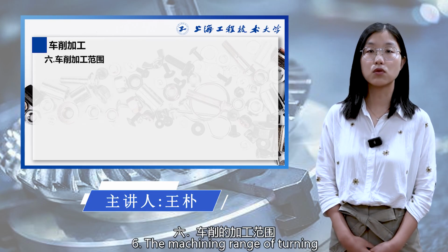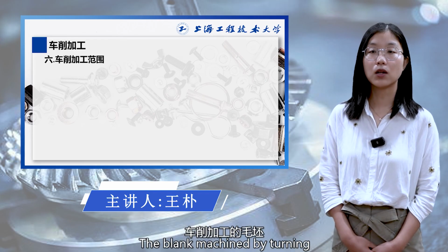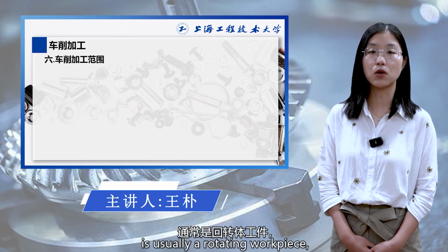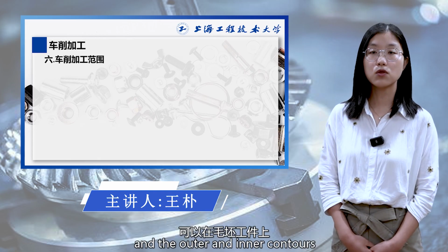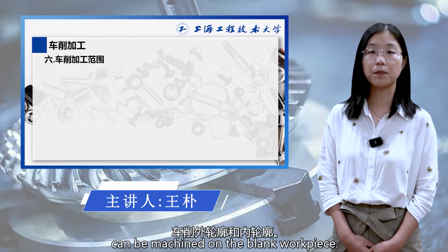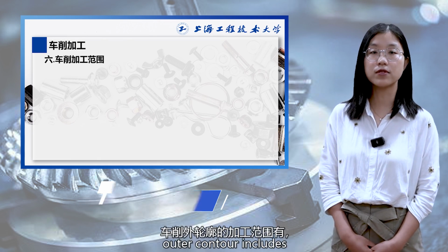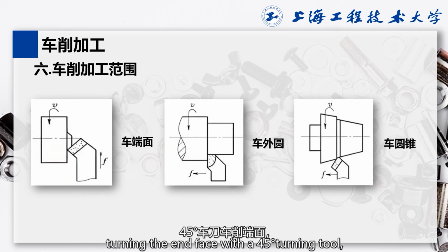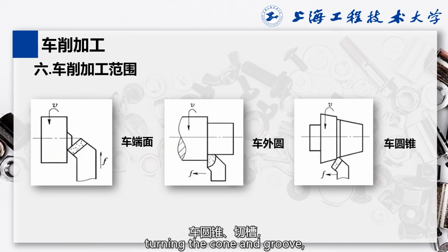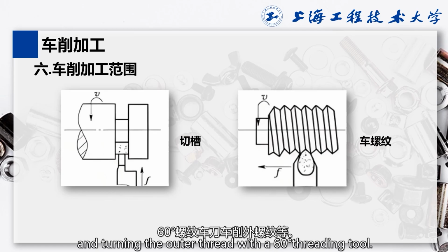6. The machining range of turning. Next, let's take a look at the machining range of turning. The blank machined by turning is usually a rotating workpiece, and the outer and inner contours can be machined on the blank workpiece. For example, the machining range of turning the outer contour includes turning the end face with a 45° turning tool, turning the outer circle with a 90° turning tool, turning the cone and groove, and turning the outer thread with a 60° threading tool.